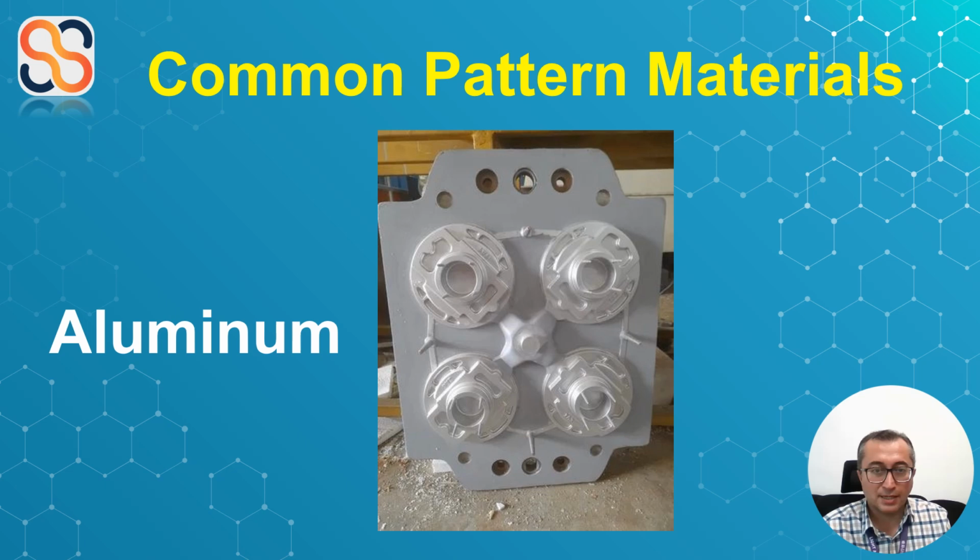Aluminum alloys can also be a good option. Such patterns are popular because they are lightweight, have a good surface finish, a low melting point, and good strength. They resist corrosion and abrasion from sand, leading to a longer lifetime. However, they don't handle rough treatment well and have poor repairability, making them best for large castings.